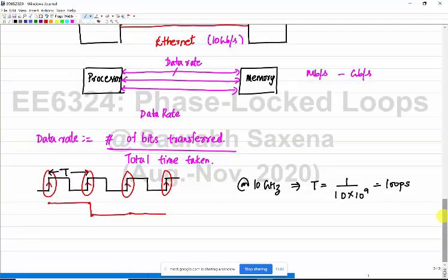So let me correct you here. When we are doing this wireline communication, the first thing is you need to generate a clock with the exact period of 100 picosecond. And if, let us say, at some point of time you do not get this clock exactly at the 100 picosecond interval, because it is generated by a circuit, you may get it a bit off, then it may become a problem.